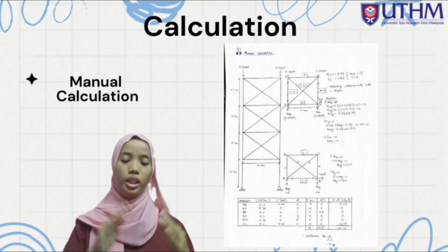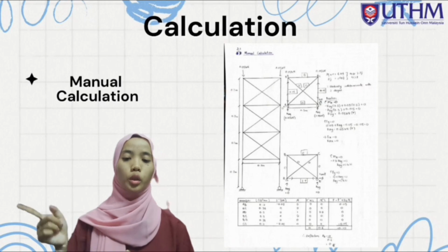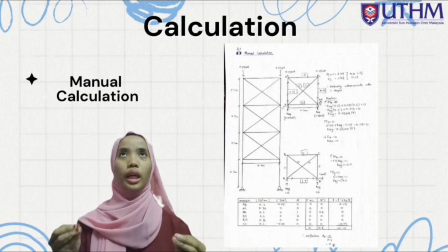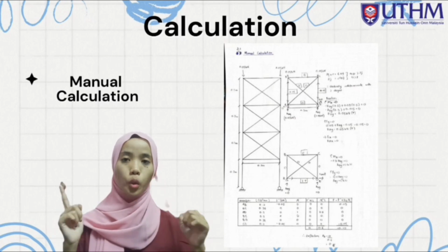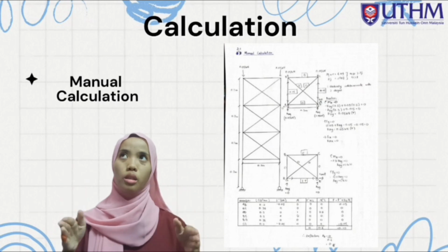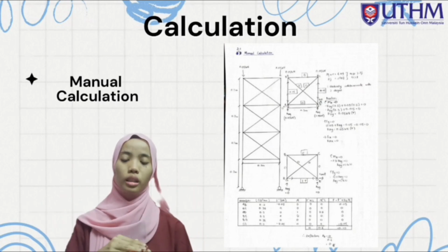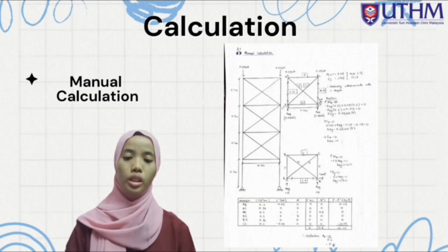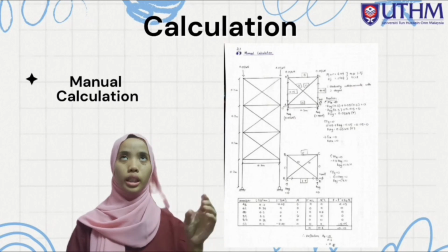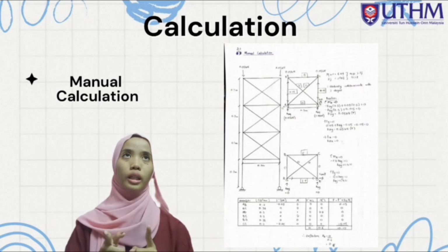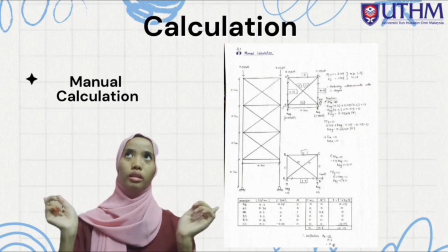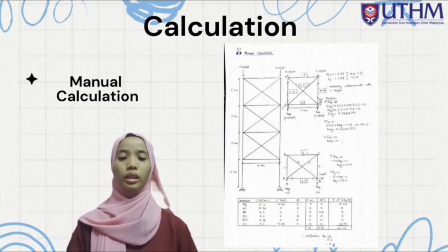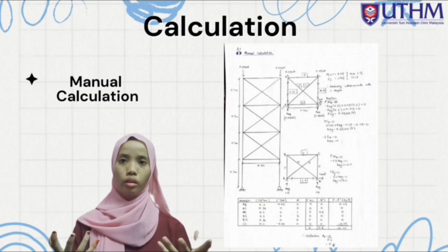Then to find the deflection, we must apply a virtual load. I put the virtual load along the X axis at point D. The reaction is also 0 because there is no load from the Y axis. From the X axis, the load is 1 at point D. So member AD is 1 tension because the load is outward. And the other members are 0 because there is no load.